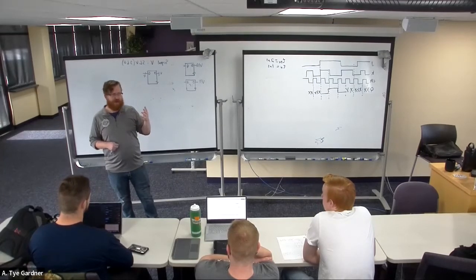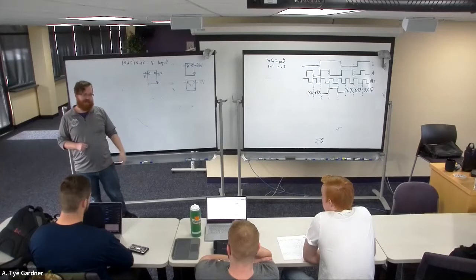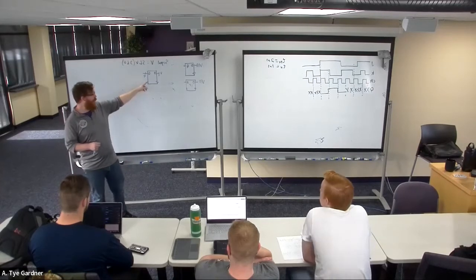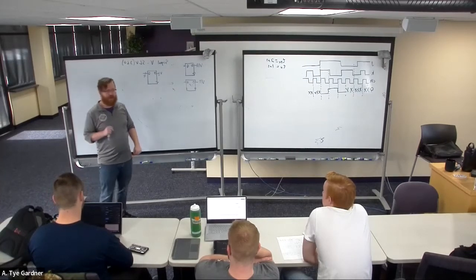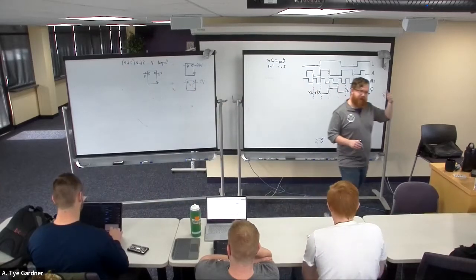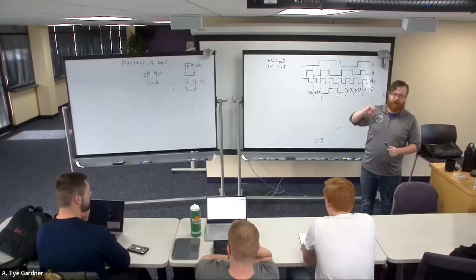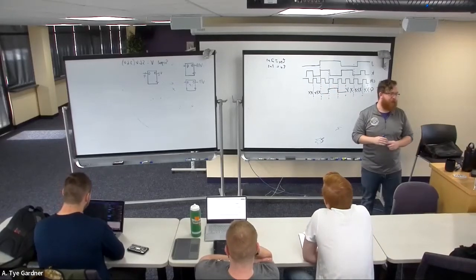So that's now 8 NOR gates. And then I have 4 D flip-flops, so 8 times 4 is 32. There are 32 NOR gates in there, based on the architectures that I've taught you, right? There are other ways to build things, but that would be the answer. Is because I want you to make the connection that this is an abstraction. There are devices inside of this that make up the D flip-flop, and we need to know how they're made.